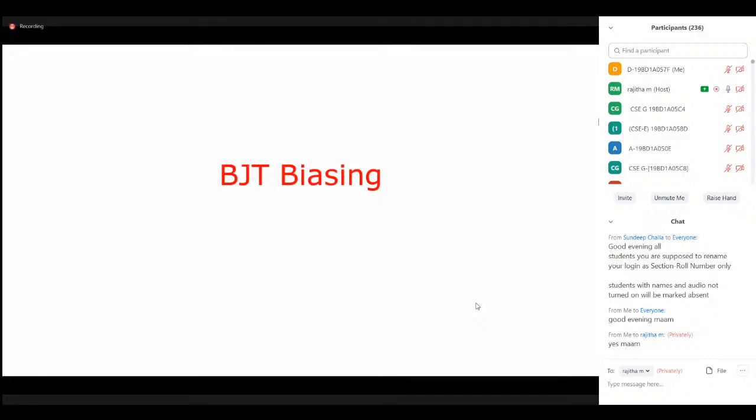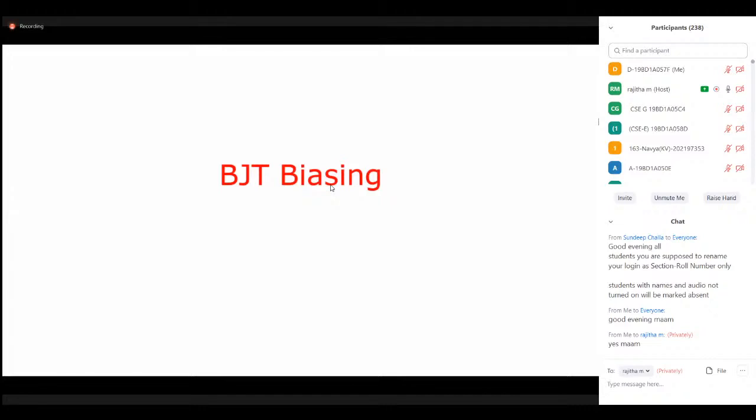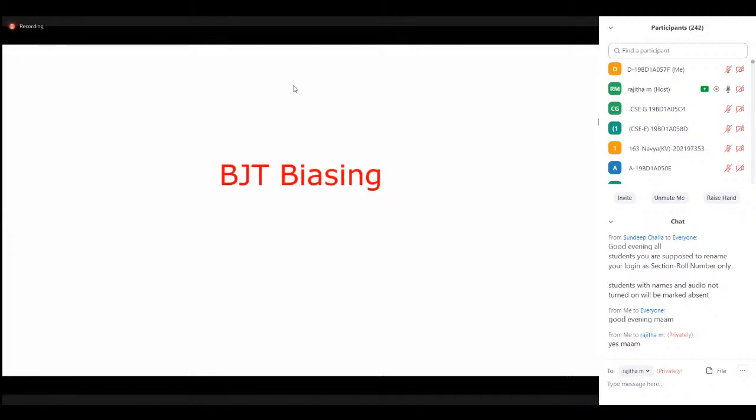When both junctions are reverse biased, there is no carrier concentration available, since our applied external biasing is 0 on both junctions. If those two junctions are reverse biased, no charge carrier movement takes place. When there is no charge carrier movement, the current flow is 0. So under the cutoff region, both junctions of the transistor are reverse biased.